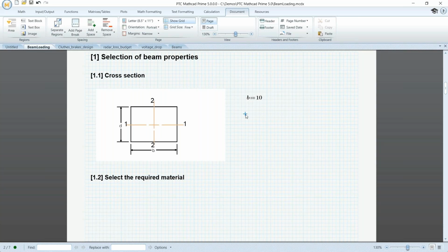So we're going to start doing some natural math notation right here, defining those variables that the diagram is showing with B and D, and then doing a calculation with those variables. So let's say I accidentally type in H here instead of D, and let's see how Mathcad handles it. It ends up giving us all of these units at the end, and we know that we haven't plugged in units yet. So we can go back and check, I don't think that's right. See that we accidentally typed in H. Now when I ask Mathcad what H is, it's Planck's constant, and it'll pop it up there for us. We'll know that that is not what I meant to type in.